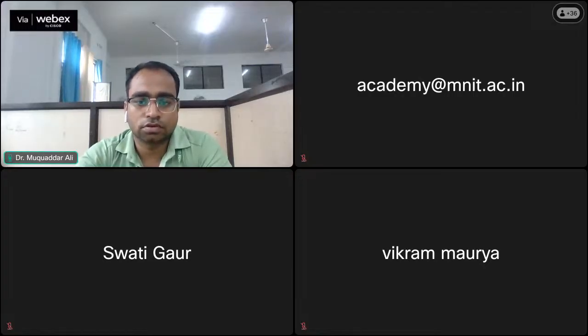Now what we are going to do, we are going to make a copy of this one. So instead of creating copy from here, I'm creating a copy by Control C and Control V, so that this is not linked with there. When you are creating a copy from here, then all the parameters will follow in the new design.